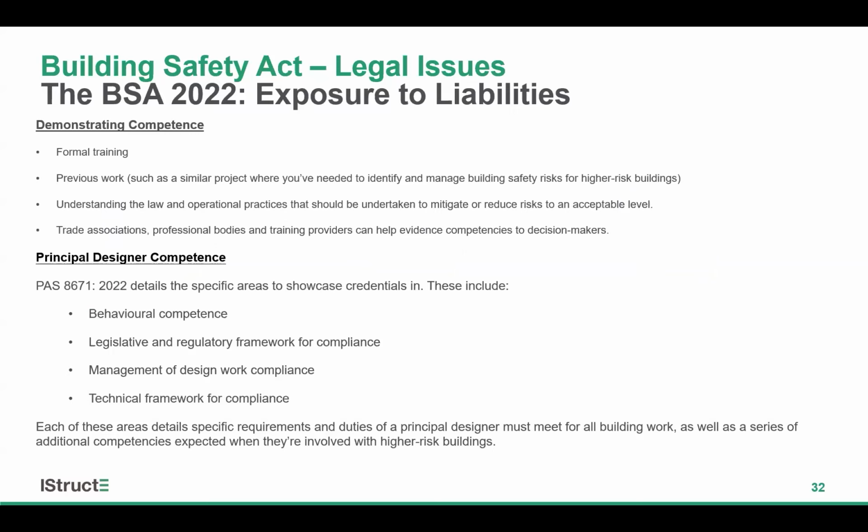Well, with regard to demonstrating compliance, there's really two key methods to do this. The first one is by training, be that formal training or accreditations, and making sure you keep records of that so that you can refer to it in the future if you need to demonstrate that competence. Alternatively, you can refer to examples or portfolios of previous work which demonstrate specific action and outcomes related to building safety. When considering the principal designer role, their competence is governed and benchmarked by PAS 8671, and it includes behavioural competence, regulatory competence, and a technical framework for compliance.